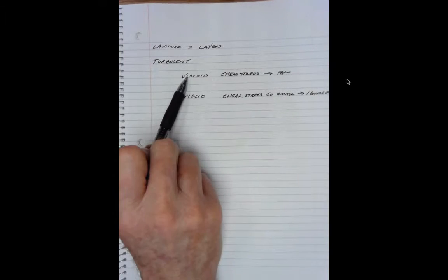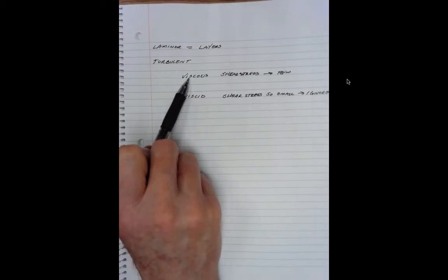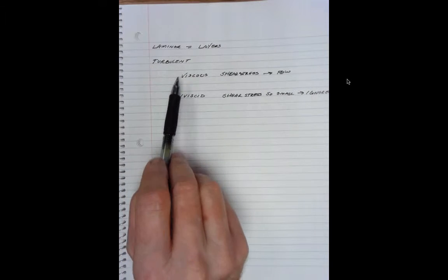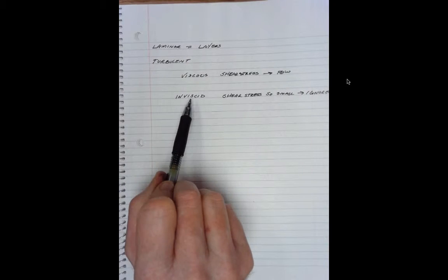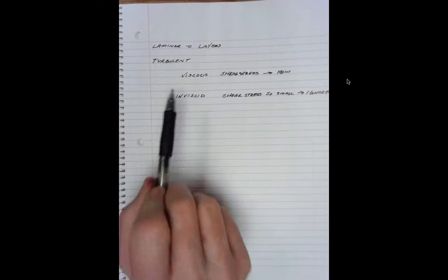Now, all real fluids are going to have some viscosity, except maybe, I don't know, supercooled helium might not. But everything else that we encounter is going to have viscous properties. But in many practical cases, we can neglect the contribution of viscosity and get a meaningful and useful analytical tool. So inviscid flow, although theoretically satisfactory and in practicality doesn't really exist, is a very useful model of nature, and so it will get used quite a bit.